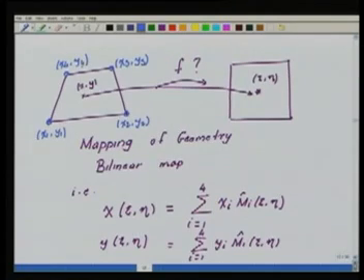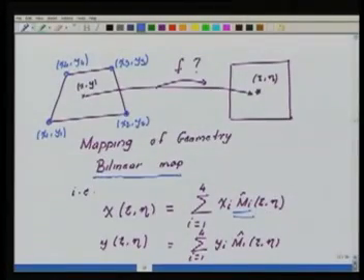Now why have I written mi? Because I want to bring out very clearly that the mapping need not always be of the same order as the approximation. Irrespective of whether I am using a cubic approximation or a fourth order, that is bicubic, quartic or biquadratic, my mapping is always going to be bilinear for this kind of domain, where the quadrilateral is straight edged.